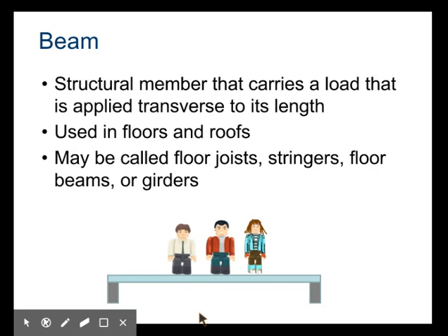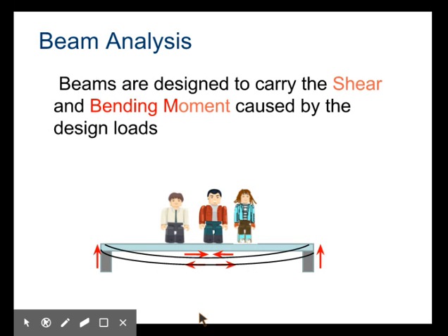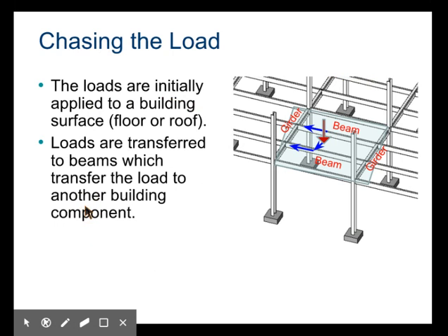So specifically floors, roofs, we refer to the floor joists, stringers, floor beams, girders, all of those things we're going to treat and throw into a large category called beams right now. The beams are designed to carry a shear and bending moment caused by those design loads. Now, the bending moment is basically how it dips down, and the shear force is a force perpendicular to that beam along the way. All right, so first things first, we got to chase the load.